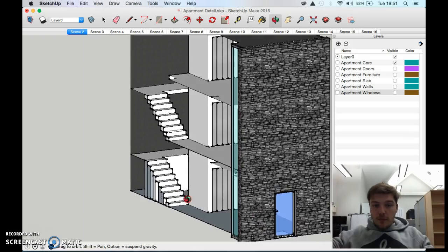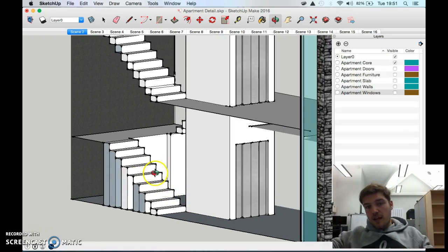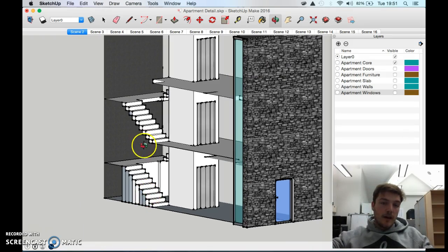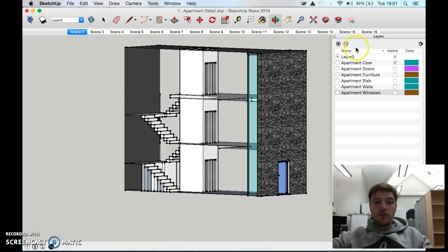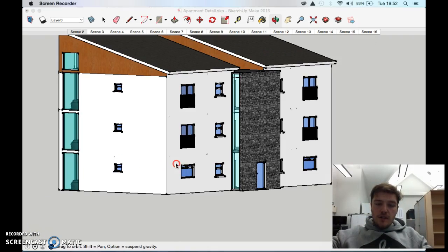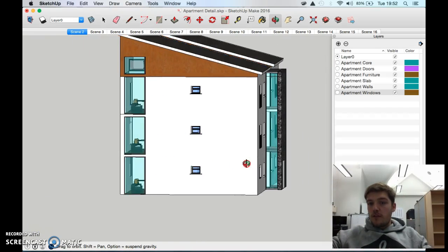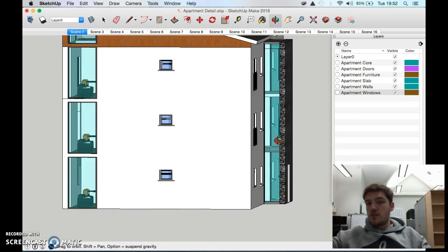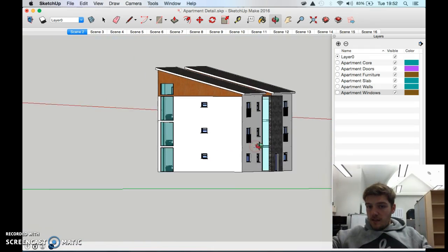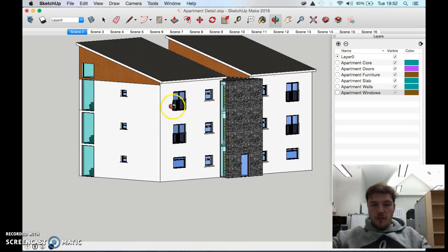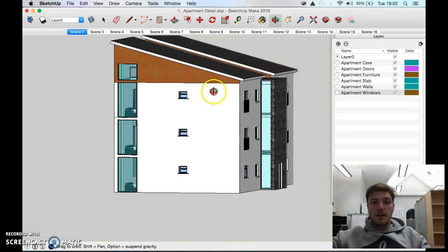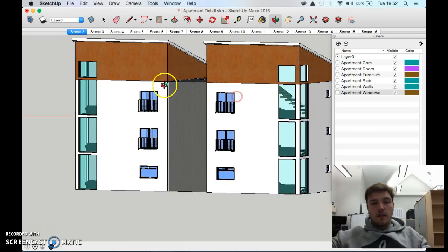As part of the development, I did have to narrow the staircase to 1 meter wide the whole way up. This then gave us enough space to be able to fit in the 8-person lift between the ground, first and second floor. You can see here, this was what I mentioned in my 2D layout, the glazed return. I feel that gave a cleaner look: the granite front, the white painted render, and then the timber around the top there.